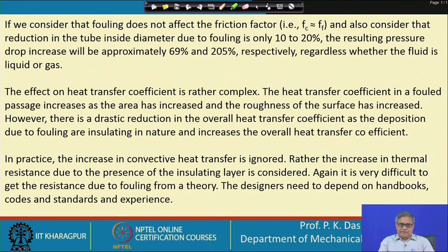It has to be kept in mind that all the standards and data books of heat exchangers will have information regarding the fouling resistance, and we have to select the appropriate fouling resistance from those handbooks. Obviously, the engineer's experience goes a long way in selection of the proper fouling factor or fouling resistance.